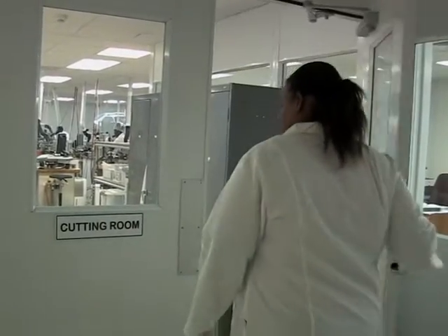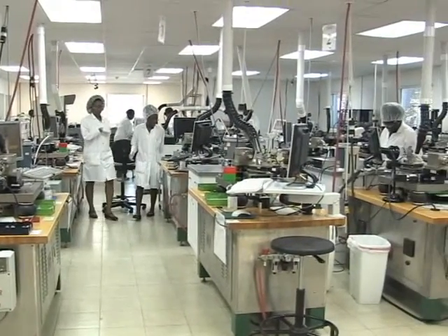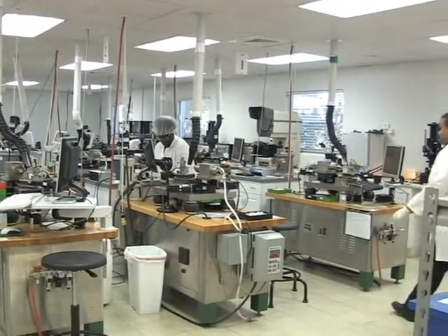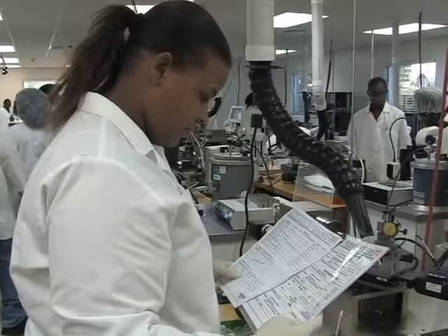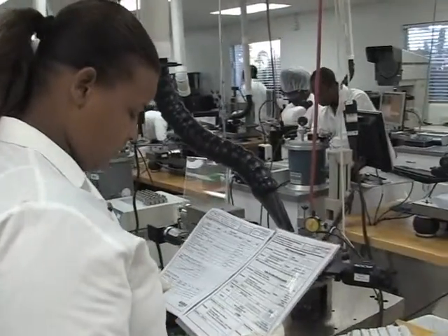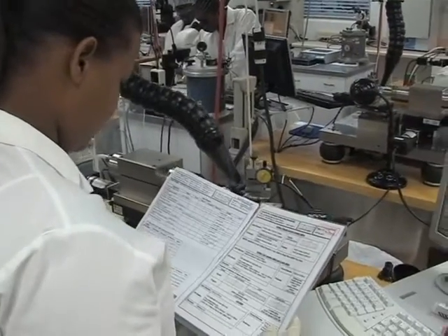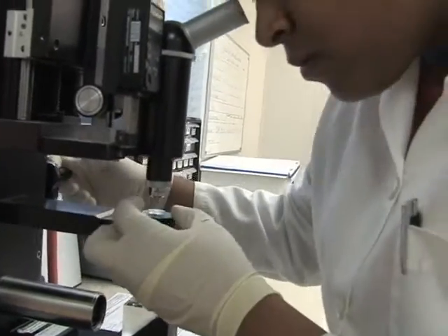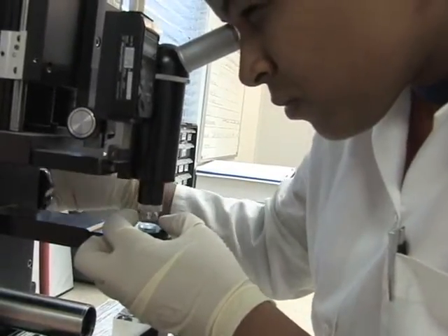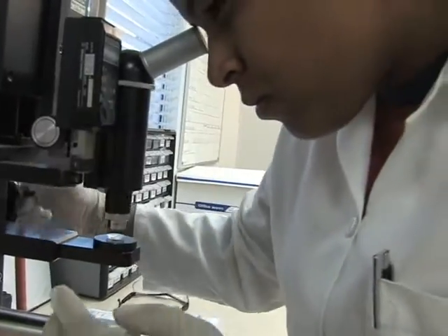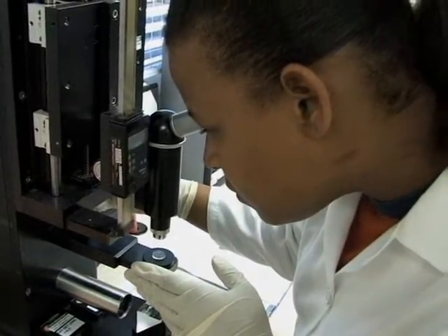In the process of making a lens, there are certain procedures that must be followed. Basically, the technician is responsible for making the lens and also for setting up the computerized lathe. Before we can start, we must first read the specification sheet allocated for the particular model of the lens being made. After the model is selected, in this case a Softet 1 model, the technician then loads the preset program on the computer, entering the power of the optic or the diopter of the lens being cut.